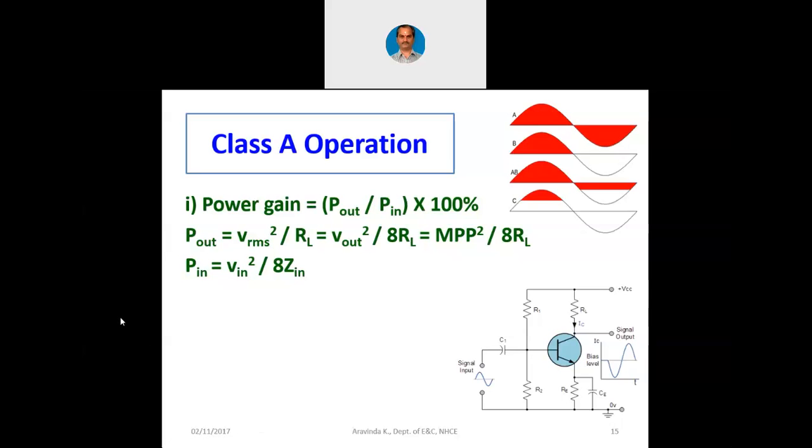Okay, no one is telling me. Let me only tell. Now here, input power is also equally strong. Unlike the small signal amplifier, input power is also equally strong, and output power is supposed to be much stronger as far as power is concerned. And we are supplying a DC power also here. That VCC and ICQ is basically the DC power, right? ICQ is the quiescent current that is flowing through the circuit, and we are giving this VCC.